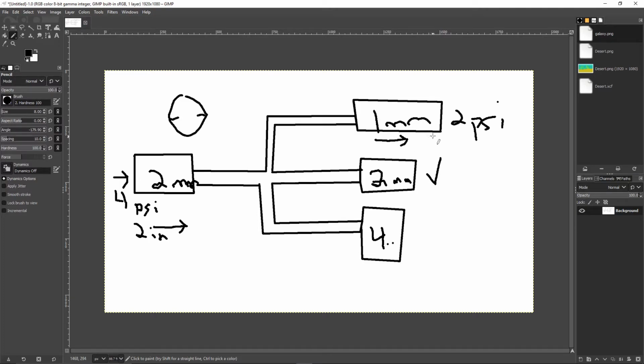So that fluid, I want you to think about this. That fluid has to go somewhere. I'm moving the same amount of fluid here as I'm moving here. But the bore that it's pushing against is half as wide. So it can't put as much force, and it will take more travel before I can use that fluid up. So if I have a smaller bore, it'll move further. And I was trying to think of an example where you would use a hydraulic circuit to do that, and I really can't.